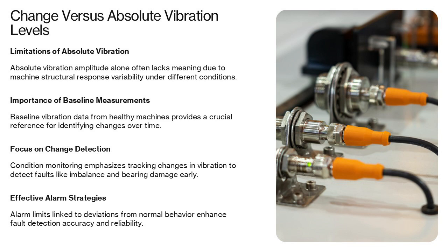Alarm limits are therefore most effective when they are linked to deviations from normal behavior rather than arbitrary vibration numbers. This philosophy underpins both calculated alarms and many spectrum-based alarm strategies, reinforcing the idea that stability and repeatability are just as important as the measured amplitude itself.